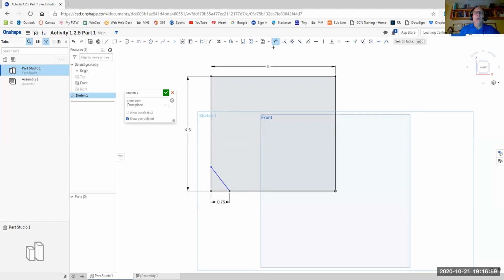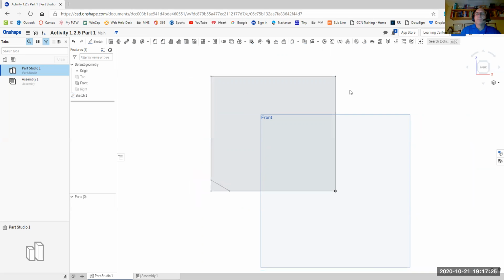The next one is an angle. So we're going to keep in our dimensioning tool. I'm going to select that line right down there, and I'm going to select this line. It's going to take me a second to grab them. Grab that one. I'll try it one more time. There we go. A little tricky to get that one. I'm going to set that there, and I need a 30-degree angle. Okay, so now I'm pretty good. I'm ready to revolve. We'll hit our green check mark.